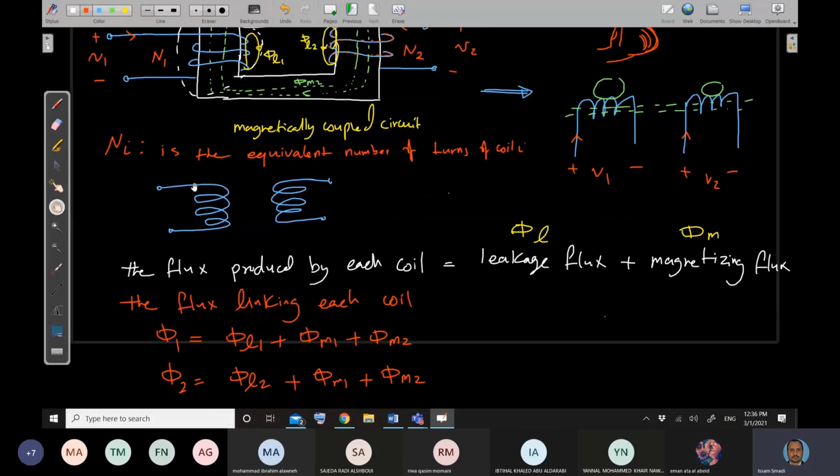So let's repeat this here, or let's start a new page. If I need to write the voltage equation, and this is valid whatever the system I'm analyzing, a transformer or an electric machine, in general the voltage equation is simply decomposed of 2 parts. One is IR plus d by dt of lambda. As we said before, this is the Ohm law, and this is due to the Faraday law of induction.